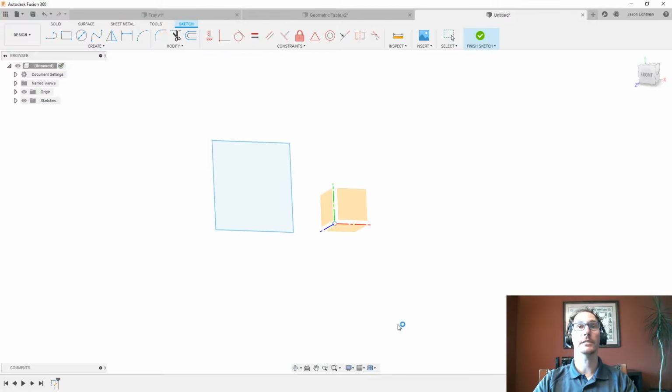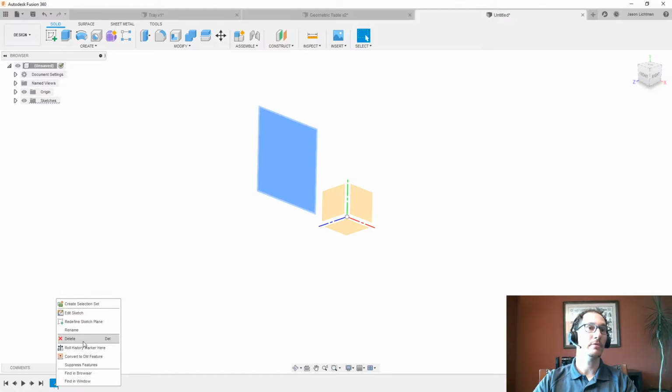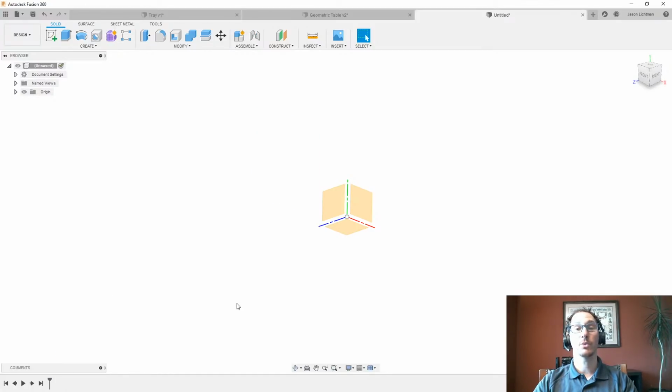If you're going to create a sketch, and let's go and delete this one right here for a moment, what you need is to start off with something flat. So you have 3 planes to start with. You have this one right here. I call it the right plane, but if you look in the upper right-hand corner, you could see that it represents YZ. So between the green and the blue there, that'll be the right plane. This plane right here is the YX or XY plane.